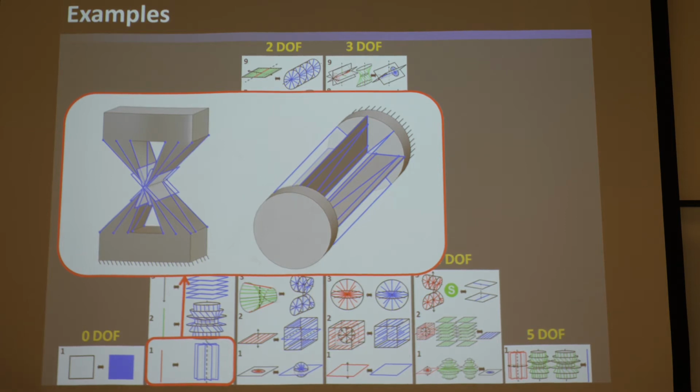Blue lines can be drawn connecting them that never exit the geometry, and they can fill the entire thing blue. Okay, so it's a parallel element, and we get a nice rotation. This one is a famous flexure that actually does a really good job with the rotation. It's basically two blades fused together at 90-degree angles connecting the two rigid bodies there. And since they're fused together, they're not considered two blades. They're considered just one parallel element that looks like that.